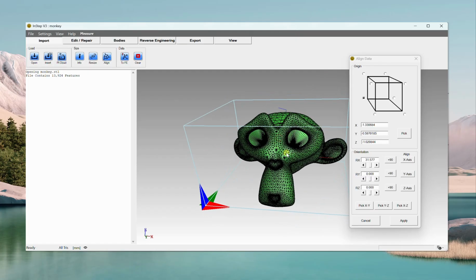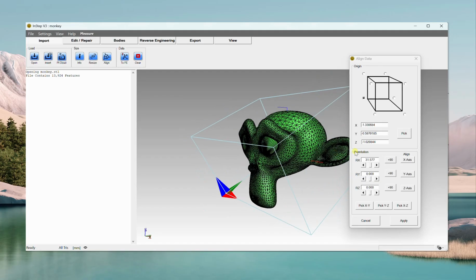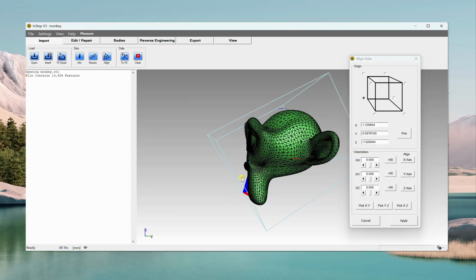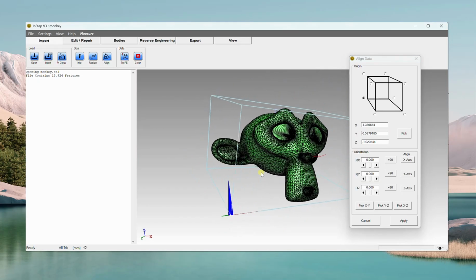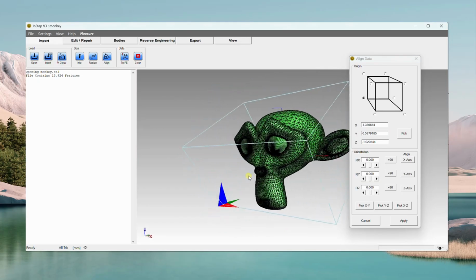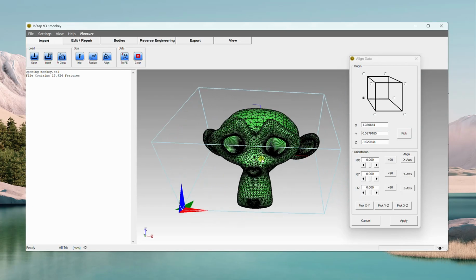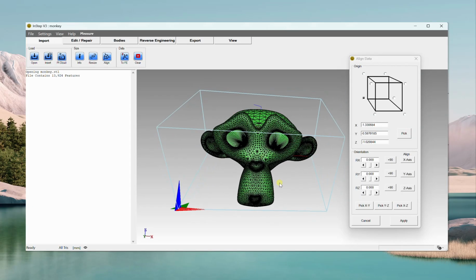If we don't want that, we can just go in and remove this. In this case it's just a rotation around X. So we can go ahead and remove that, set that to 0, and you see a little animation. It orients it back to matching the origin. Now let's say we wanted to import a second one of these shapes that is offset along the X, for example. Right now the origin here is at minus 1.33.